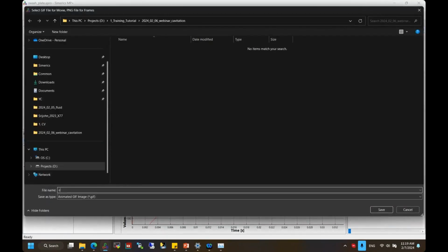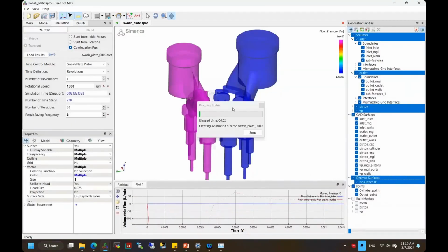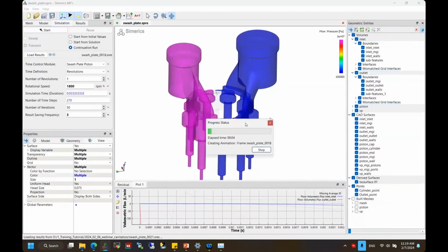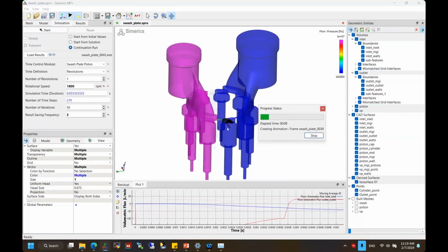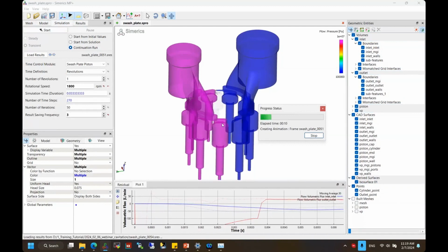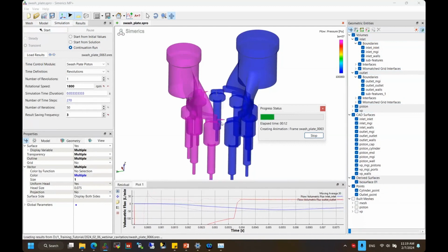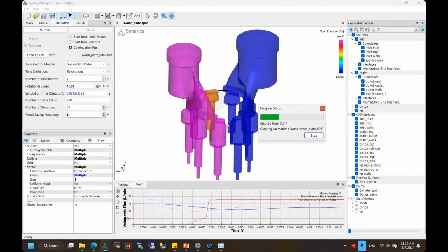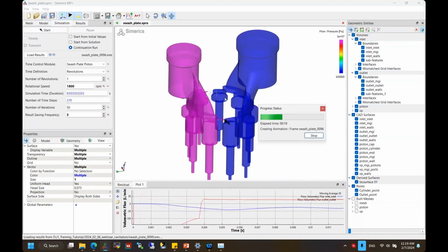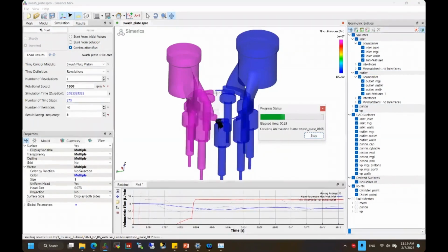So cavitation. Essentially, it's going to load the results one by one, and then generate this animation. You can also see we have this selecting mesh, and those cavitation bubbles or the jet are generated each time when the piston volume connects with the inlet and outlet port.